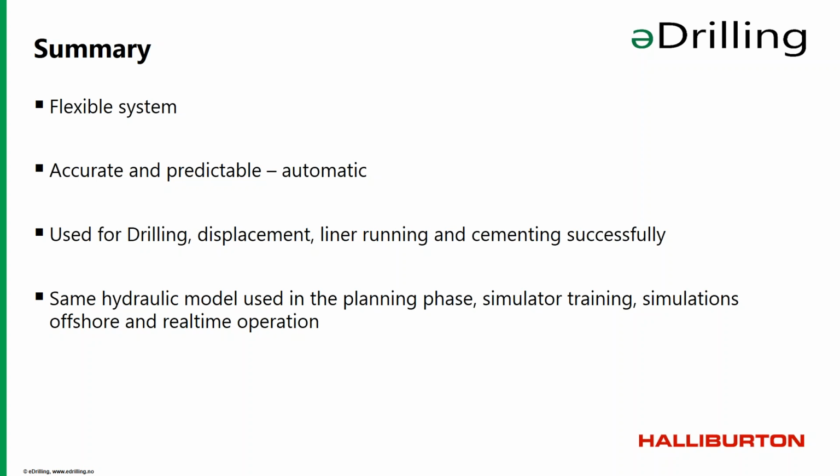Okay. So a question regarding the flow out detection with the Coriolis meter when you get gas. What we see is that the Coriolis meter is very good on one phase fluid. It's very good on just the fluids and also on just gas. On a recent operation not long ago, we had gas concentrations up to close to 40%, and we still had good flow out readings. The Coriolis meter signal didn't drop out. We had signal readings all the time.